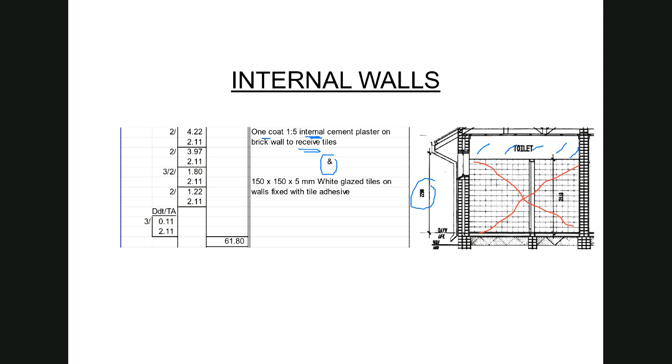It can either be bedded in a cement plaster bed, or it can be stuck on with adhesive. So when you're using a tile adhesive, you plaster through behind the tiles. If you're using a backing, the plaster becomes your backing and you do not have the 2 measures. But that's just for background information.